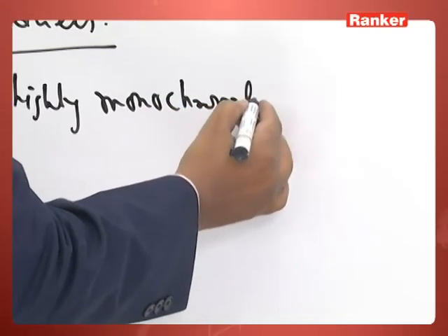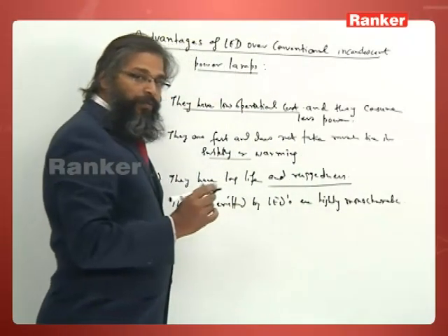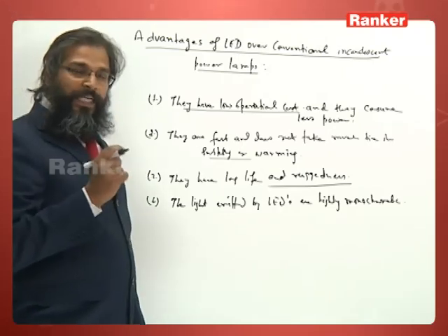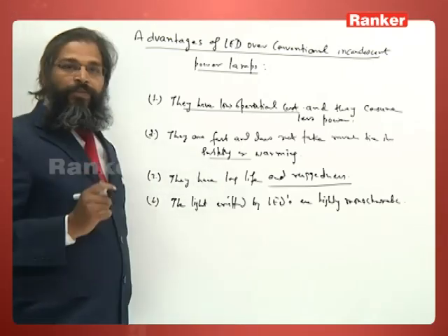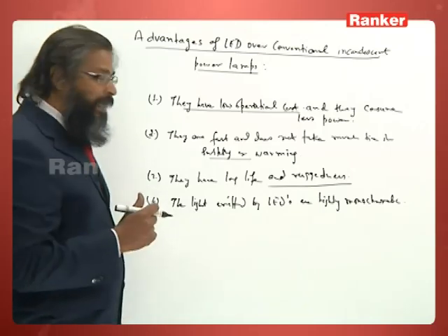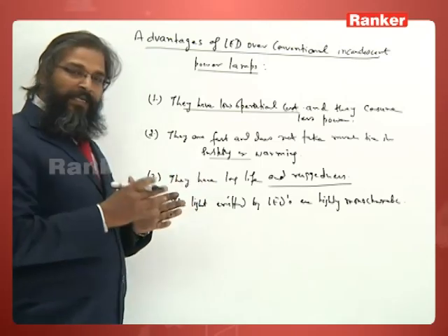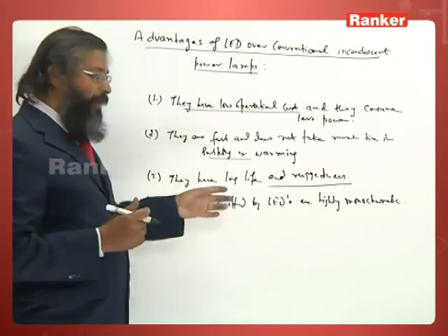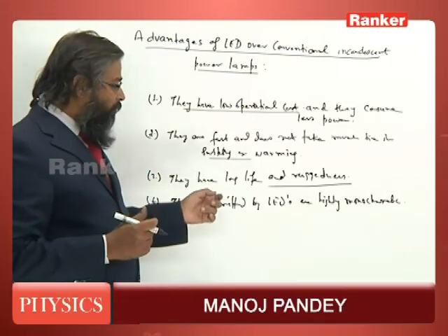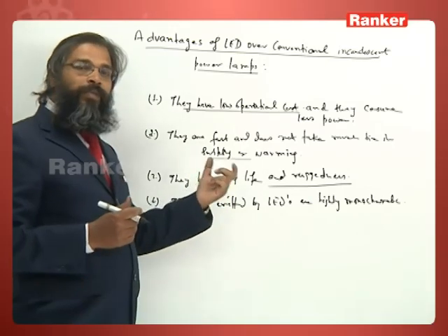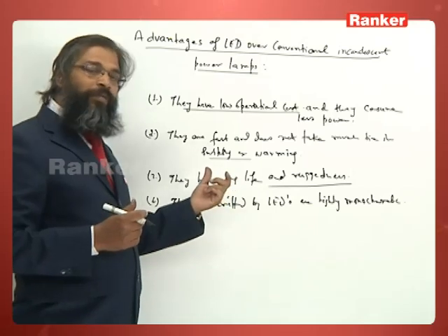monochromatic. If I want red light, it will give a very highly monochromatic light, that means only red light will be given, but an incandescent bulb will give a lot of wavelength spectrum from red to yellow like that. But if I say it's a green LED, the wavelength will be very precise, the bandwidth of the variation will be very small.